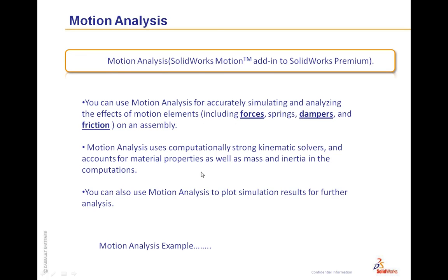Our third option in the motion manager is motion analysis, and that one does require SolidWorks Motion to be able to work. When you get into motion analysis, this is where you can accurately simulate and analyze things like forces, springs, dampers, friction with material properties. There are kinematic solvers that can solve for the material property and how friction affects that. And as it says here, mass and inertial computations as well.